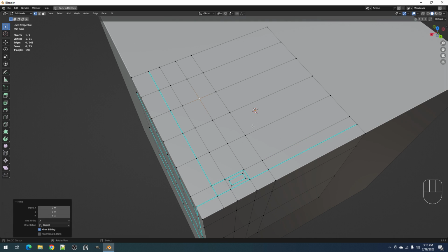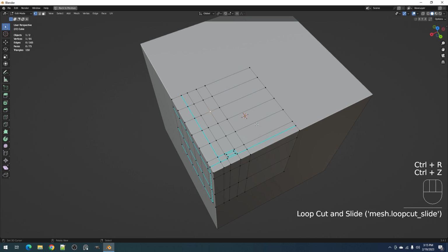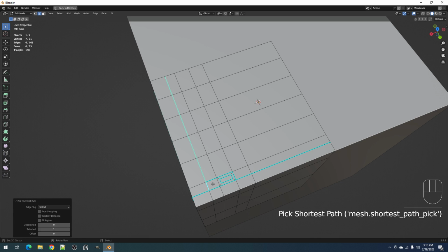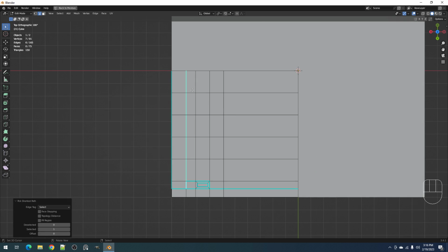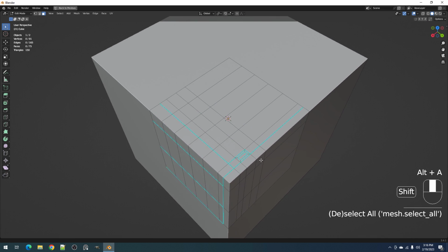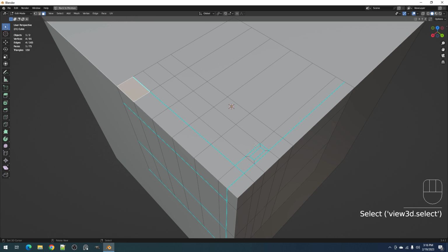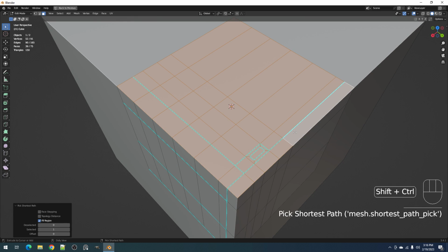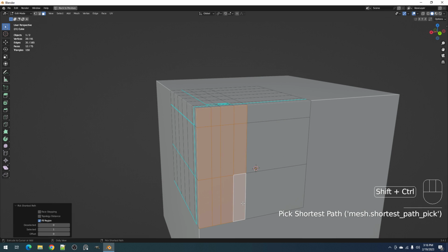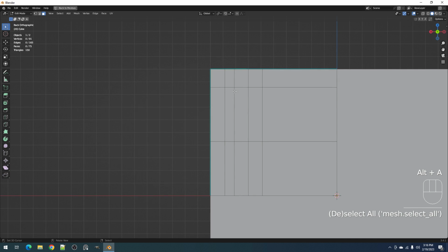Those are just a few of the tools that you can use to generate the edges in the mesh. And after you've designed the edges, and then you must be contiguous, remember, then you must select the faces that include those edges. So basically, you select the faces first in your mind. So for example, I want those panel cut details here in this part. Then you design the panel cut detail here, using these border faces or sets of faces.